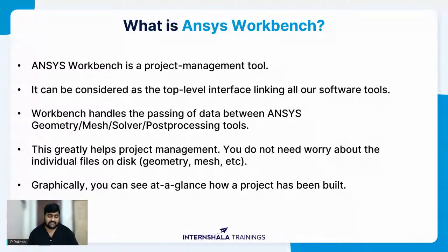Before going to the ANSYS demo: inside ANSYS, we'll have different modules for performing different types of operations. For example, if I want to create or import geometry, I have a module known as DesignModeler. Likewise, if I want to do meshing, or apply loads and boundary conditions, for that I have ANSYS Mechanical. Likewise, if I want to create materials and other stuff, I have a module called Engineering Data. So ANSYS Workbench, on a top level, can be considered as an interface which links all these modules together,